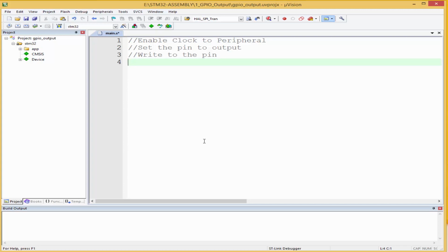This is employed to help the microcontroller consume less power. And what this means is you only allow clock access to a peripheral when you need it. So over here, by default, all peripherals have no clock access. Because we're going to use the GPIO, we're going to use a particular GPIO actually, which is GPIO A. We allow clock access only to GPIO A, so that's the only part that the clock is connected. So that is why we need a step.